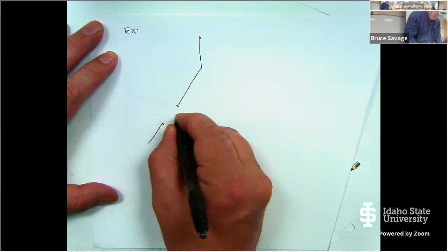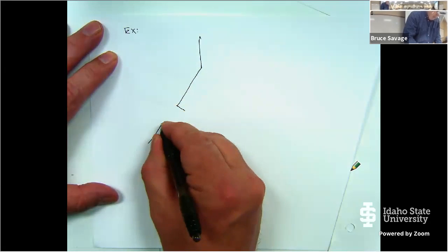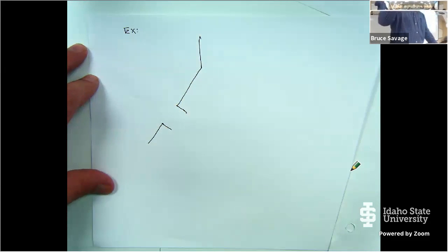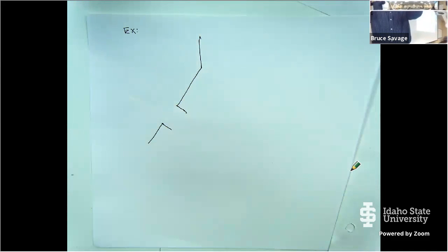And a butterfly valve is simply like a flat plate that has a shaft going through it. So if we have a round pipe, and we put a plate inside that would block the pipe, perpendicular, it's the exact area that would block the flow in that pipe. And I put now a round shaft through that plate.